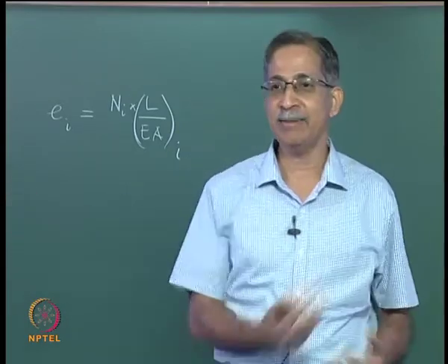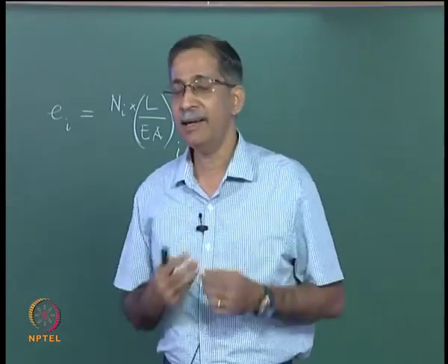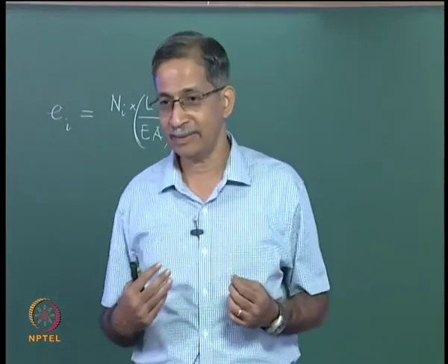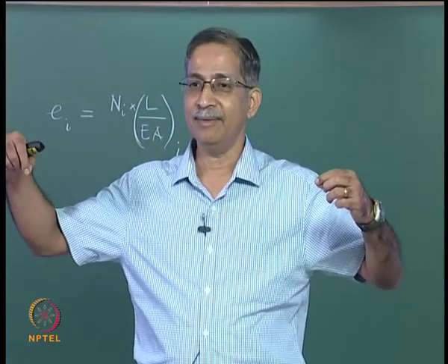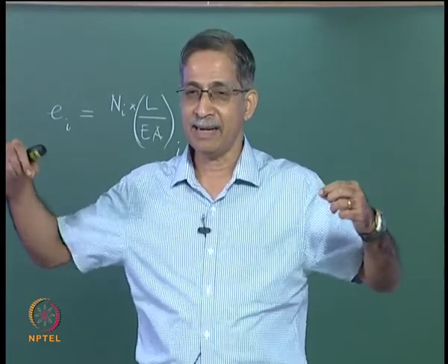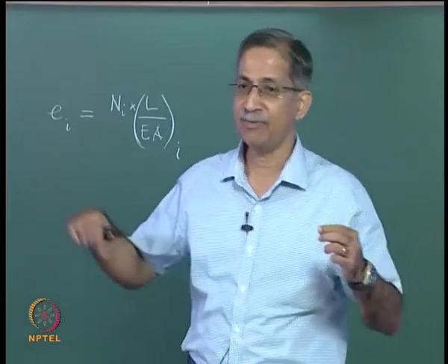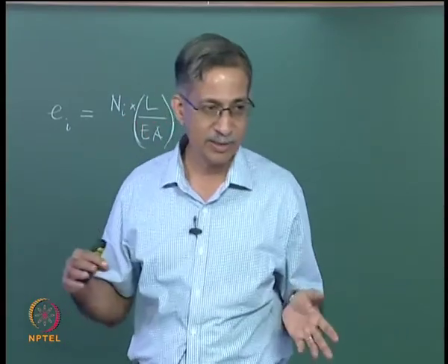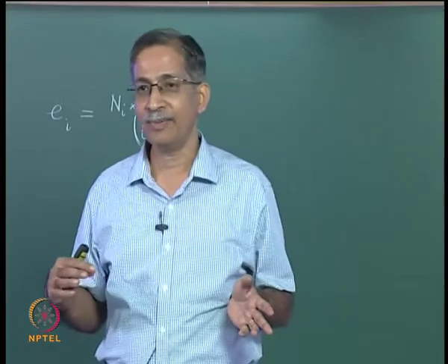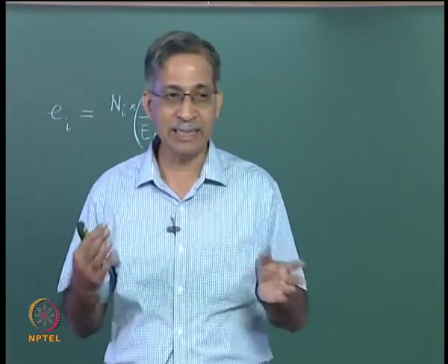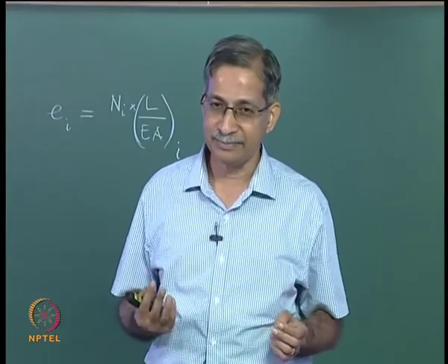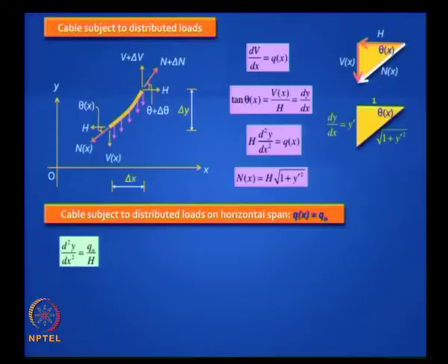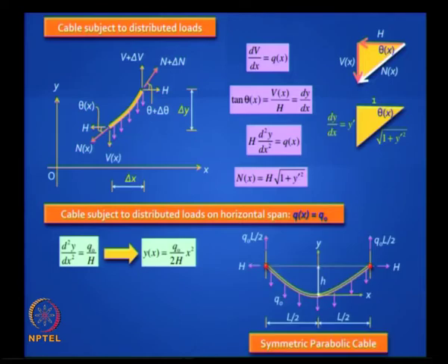What is the shape of the cable in suspension bridges? It is parabolic. Why is it parabolic? Because of uniform loading. Right. It is parabolic, with the idea that the parabola is the ideal shape, the funicular shape, when you have a uniformly distributed load. So you need to ensure that it will remain a parabola even when vehicles move on the bridge. How do you do that? You have to make the deck stiff.